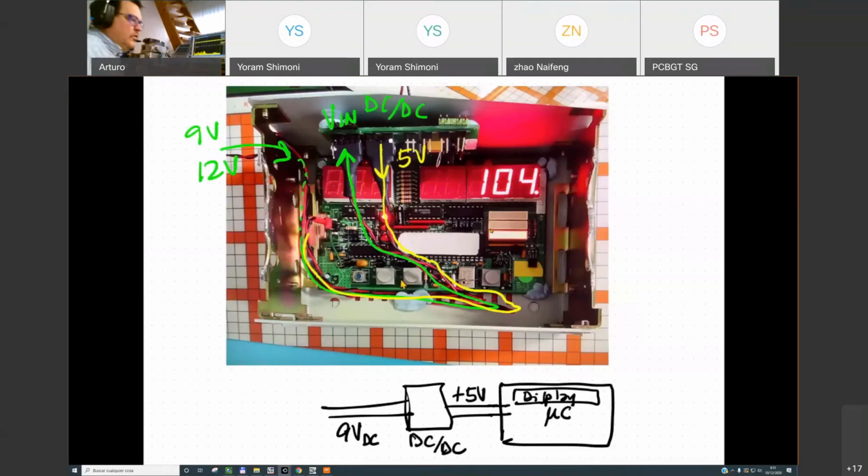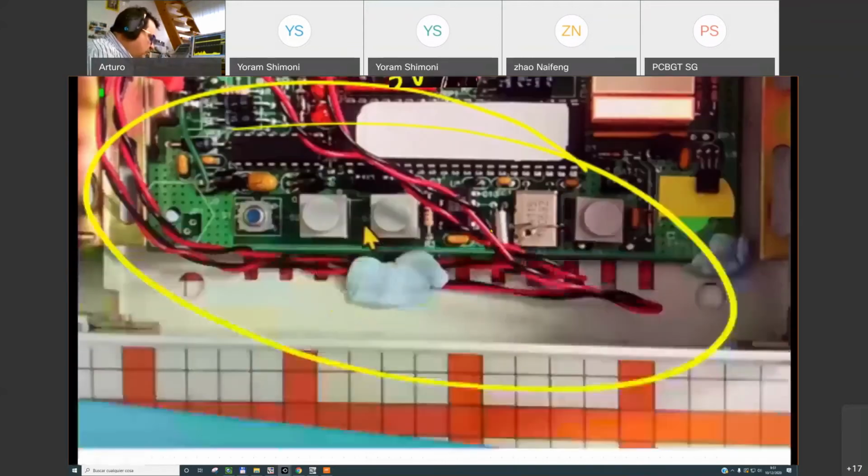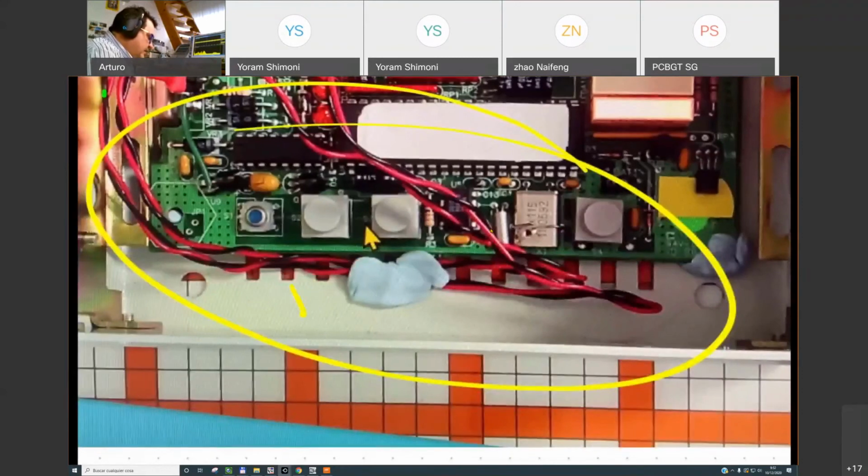Okay? So what happened, basically, you can identify that the cables carrying the power supply signals have a layout that is close to the slots for ventilation. This is a general rule of EMI when designing circuits.